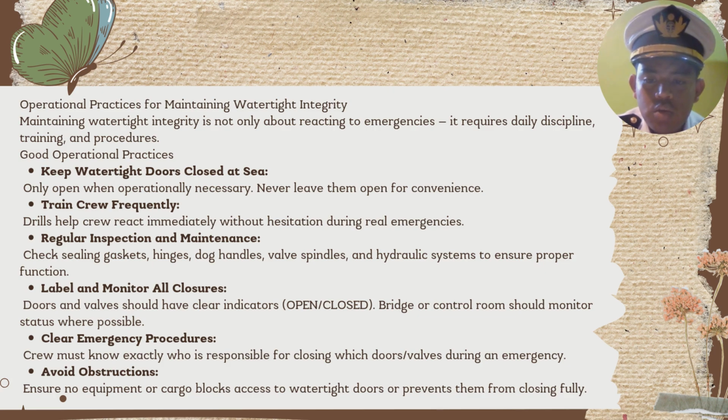The next, train crew frequently. Drill help crew react immediately without hesitation during real emergency. The next, regular inspection and maintenance. Check sealing gasket, hinges, dog handle, valve spindle, and hydraulic system to ensure proper function.